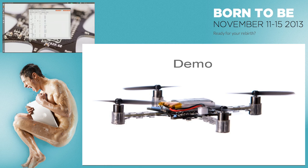So yeah, again, it's not very pretty, but that's what we have so far. These are all variables that are set up in the code of the copter for logging. It's a single C macro, and they all become available from the PC client. The story is that during our development, some of us were really interested in high performance logging, and we're doing very, very custom things, packing as many bits as possible in one radio packet.